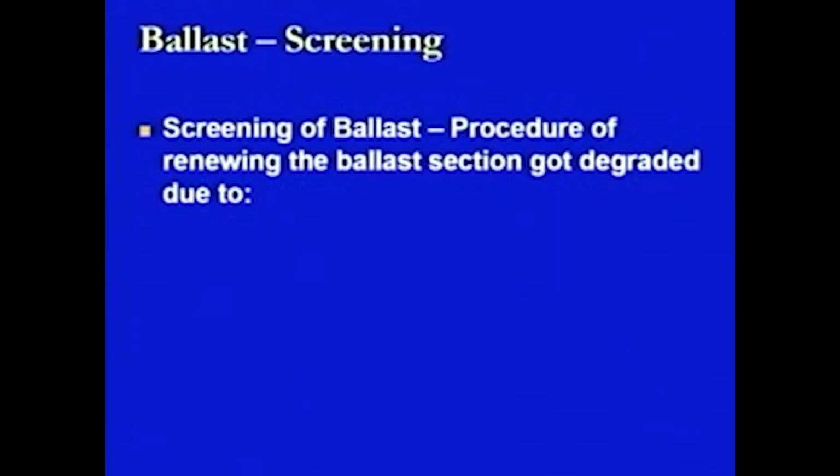Screening of ballast is a procedure of renewing the ballast section which has got degraded. What happens is that with time, as the ballast is used for a longer period at any location, as the loads keep on coming from the top, or there are other weathering agencies which have their role to play in the degradation of that material, this material keeps on reducing in size or keeps on losing its strength.